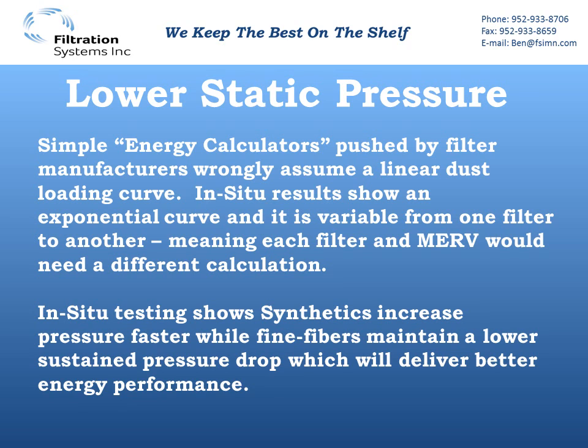But there were two main assumptions that were wrong with these energy calculators. One is they assumed a linear dust loading curve, and that just doesn't happen. Dust loading curves tend to be exponential. They'll stay low and low and low, and then they'll hit a point of loading where the pressure drop goes up rather quickly. Each filter and each MERV would need a different calculation if we were really going to do an energy calculator correctly and accurately to what is going to be realized in the real world.